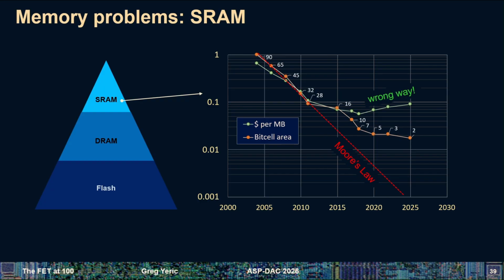It's going to vary around that number, and if you use the same stepper for a future node, the full variation number is not going to change, but the percentage of variation in a smaller transistor is going to go up. And there's other reasons why you have variation, random dopant variation and stuff like that. So anyway, that's the problem, is that the SRAM bits are just not stable. You can't make a working SRAM if you make it any smaller than we have today, unless you do something to reduce variation.